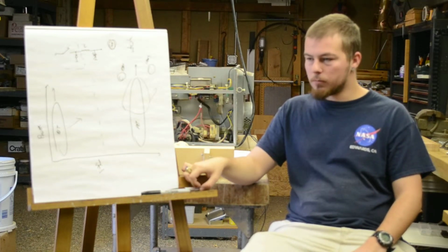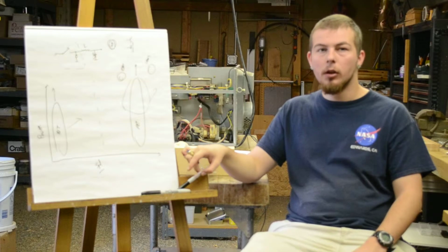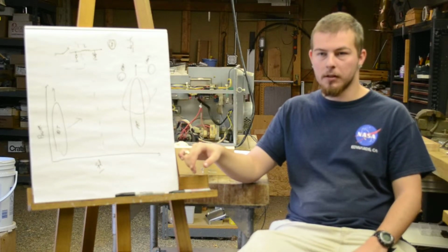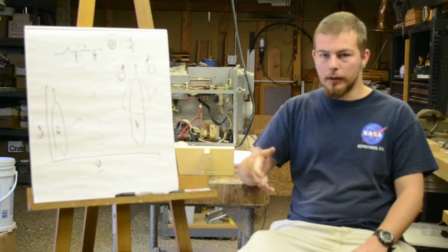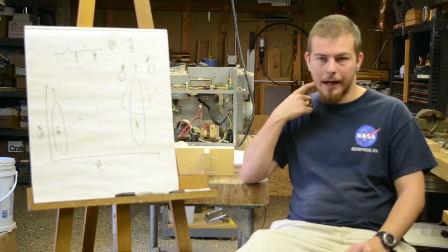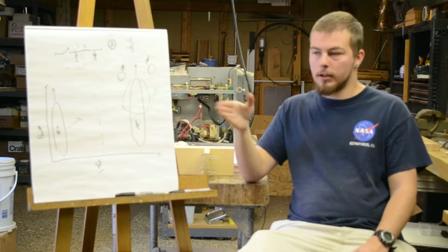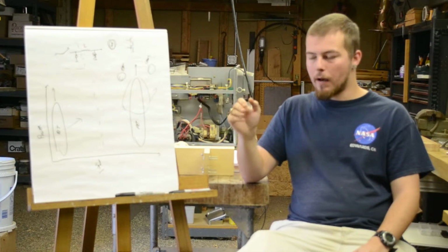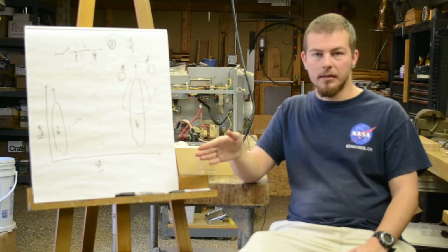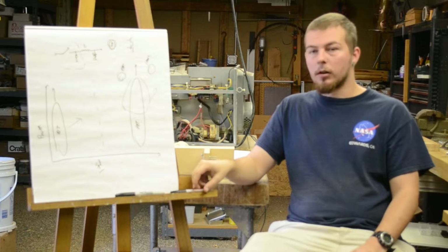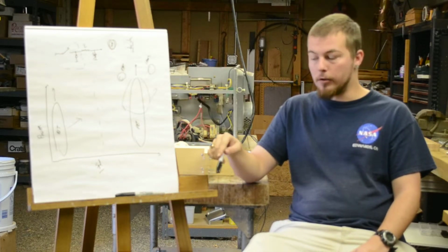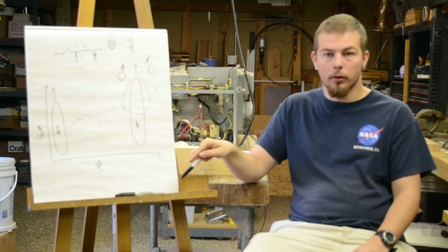As far as the relatively impractical, you have the transformer and inverter based designs where you literally invert the signal to turn it back into AC. You ram it through a transformer to convert the step ratio and the turns ratio, and then you rectify right back into DC. Now that works, and you can adjust a number of parameters to get the same output.